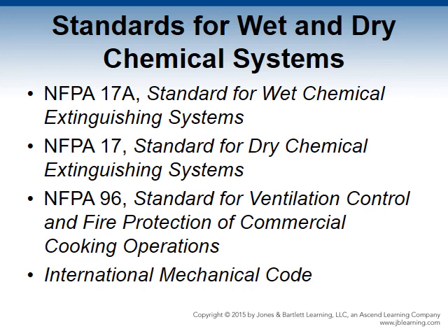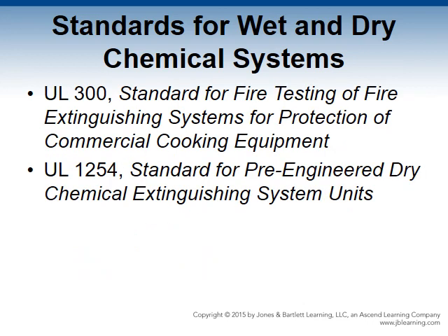The International Mechanical Code covers the ICC-based requirements. Underwriters Laboratories: UL 300, the standard for fire testing of fire extinguishing systems for protection of commercial cooking equipment. UL 1254, the standard for pre-engineered dry chemical extinguishing system units.